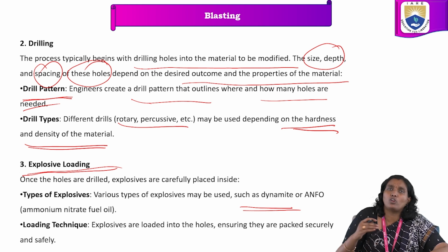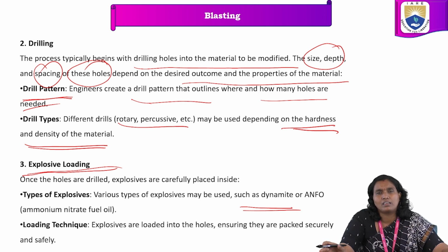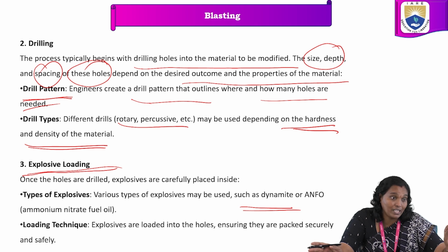Explosives are loaded into the holes, ensuring they are packed securely and safely. It is very, very important. At the time of loading, we have to follow the safety precautions and the prescribed safety rules. The material we use and the time needed depend on which type of explosive we are using.